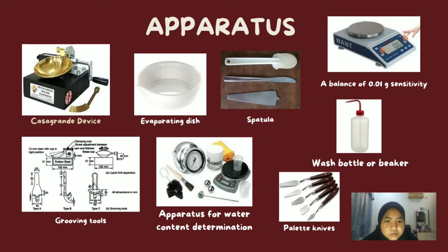Today I would like to present about apparatus. The apparatus that we use are a Casagrande device and operating dish, spatula, a balance of 0.01 gram sensitivity, wash bottle and palette knife, and the last one is apparatus for water content determination.